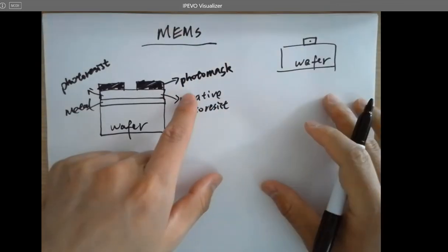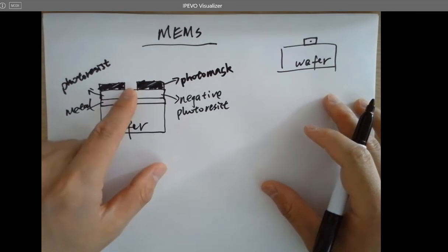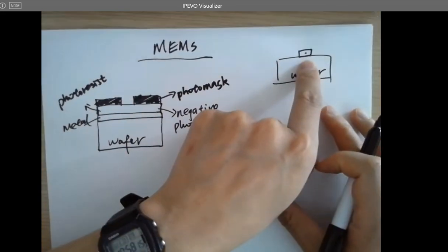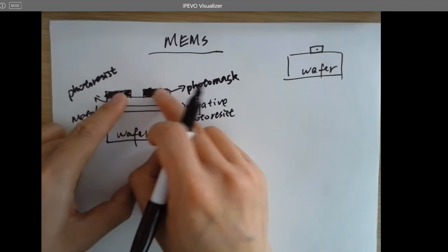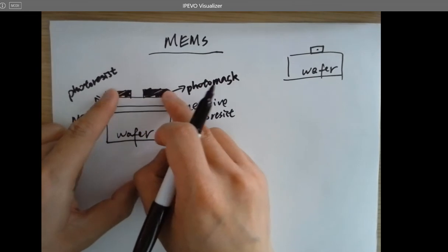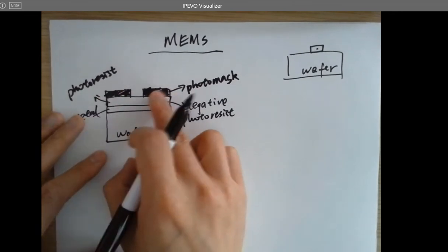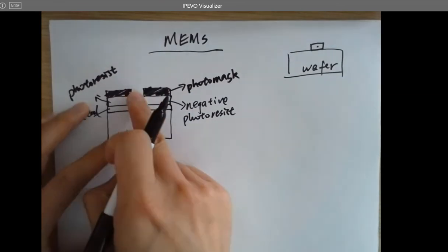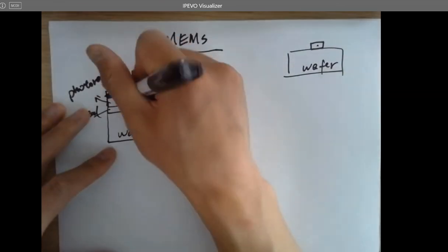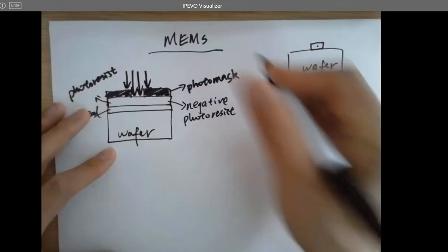This allows you to design all the shapes you want to finally be left on the top of the wafer. So now I leave the opening, because all the other areas are being covered by ink. Because you printed out that sheet, this part is transparent, and then you expose UV light from the top.